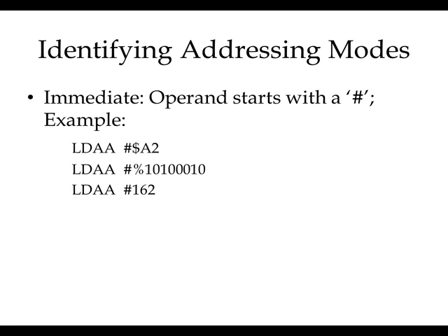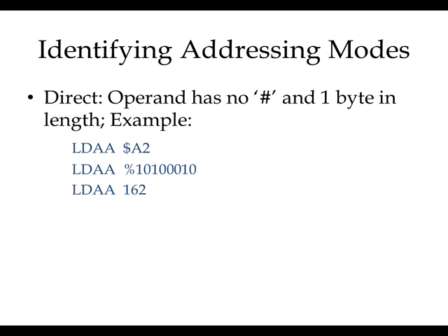Do you see these 3 examples? See, all these 3 are LDAA, but the operands start with a hash. So right away we know that the mode is immediate. Any question here? Too simple. Now let's look at the next one.